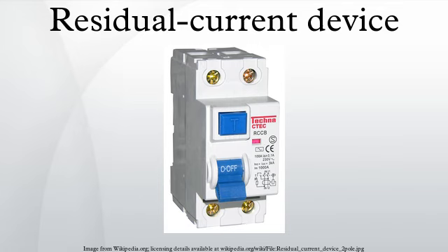An RCD will help to protect against electric shock where current flows through a person from a phase to earth. It cannot protect against electric shock where current flows through a person from phase to neutral or phase to phase, for example where a finger touches both live and neutral contacts in a light fitting. A device cannot differentiate between current flow through an intended load from flow through a person, though the RCD may still trip if the person is in contact with the ground as some current will still pass through the person's finger and body to earth.